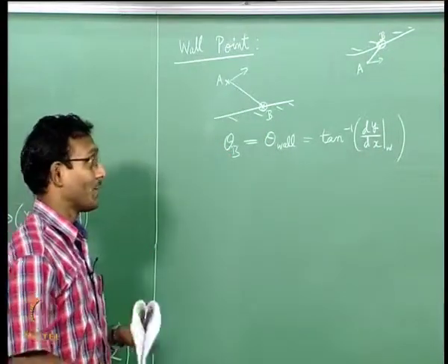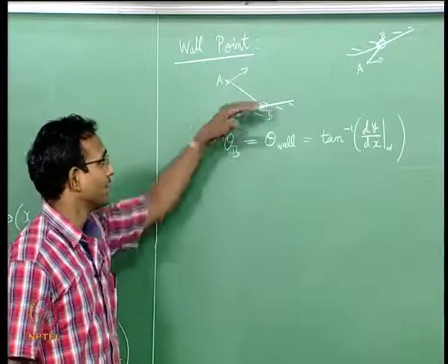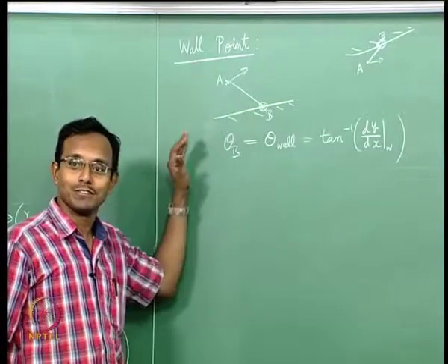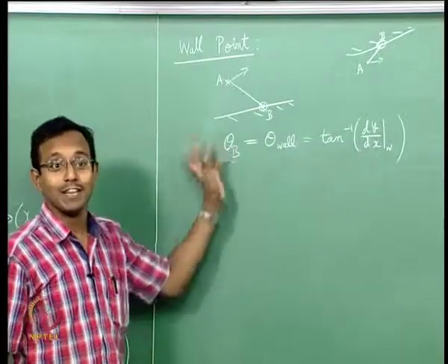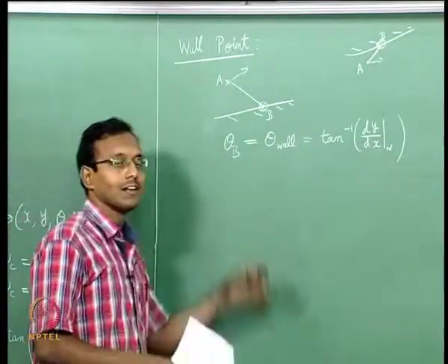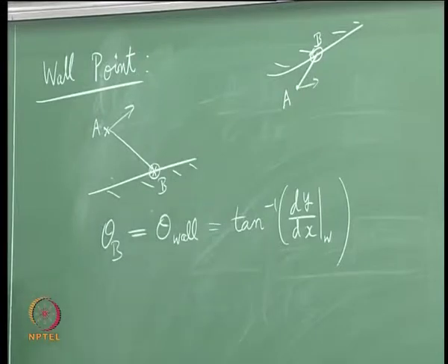But of course, I do not know the point yet. This may be a curve and the slope may change from point to point. I do not know the exact point, but I can find slope at any point. So I can find theta at any point. The next thing you have to think about, if it is a right running characteristic, theta plus nu is a constant.